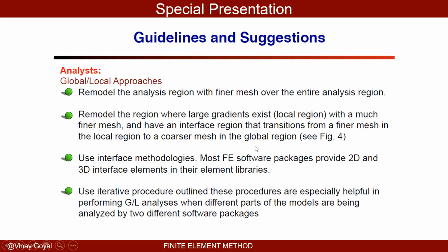I knew exactly what was going on, but I didn't want to tell him because he's senior to me and it would be like a slap on his face. He is using K minus omega squared M equal to a null vector. You are looking for the eigenvalues of K minus omega squared M. K is a stiffness matrix, and the stiffness matrix of a free structure is singular.